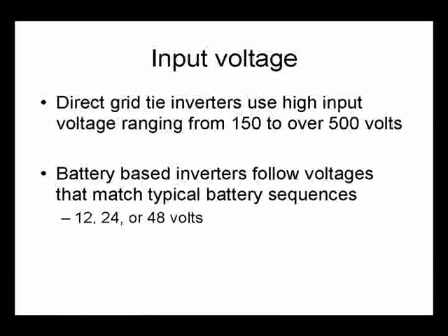If it's a battery-based inverter, you will usually be working with denominations of 12 volts. 12, 24, and 48 are the common input voltages. 12 volts, I think, is a device of the past unless you're doing something small. Like you want to plug it into your car, okay, you got 12 volts, great. Get a 12-volt input inverter. If you're doing something like a cabin or a home, 12 volts really isn't the way to go anymore.